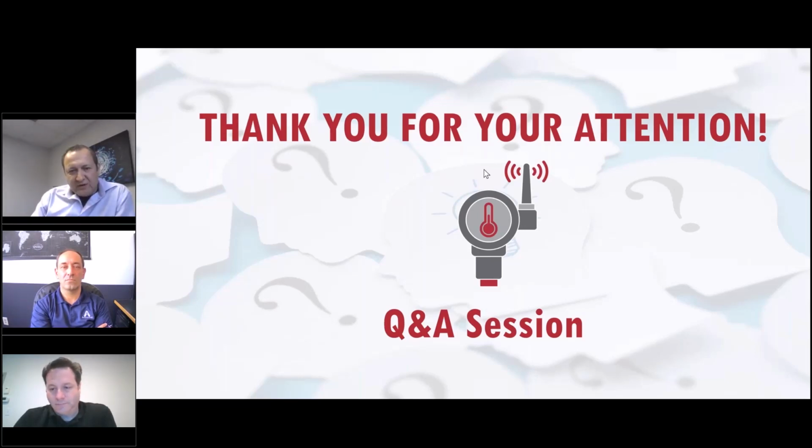That is one milestone or phase of the design where a lot of effort typically goes in, and it requires deep embedded firmware knowledge and hardware knowledge. So it's a time-consuming phase of the development project. I would highly recommend that when you embark down this road of developing an instrument, you very carefully plan for battery life from the very get-go.